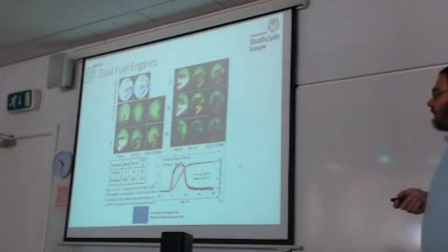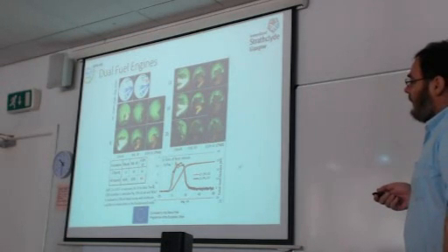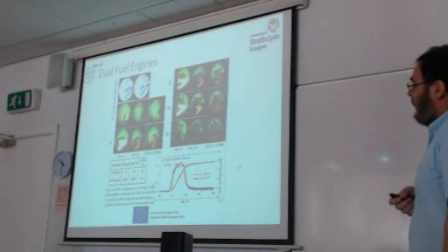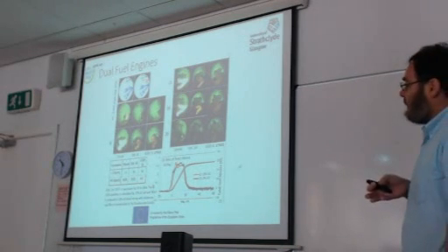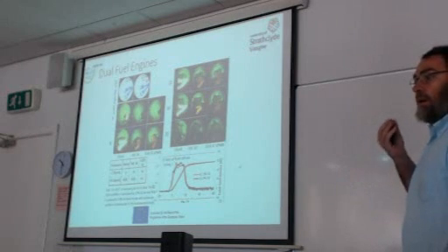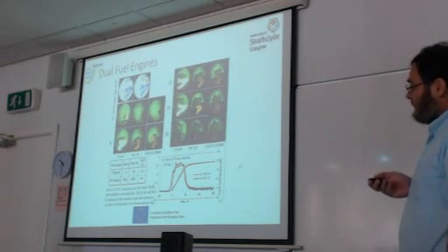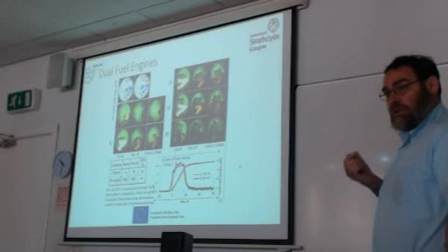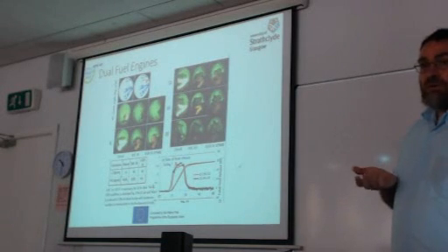If you consider that combustion of a liquid fuel is complex, then the combustion of a gaseous fuel and a liquid fuel is certainly more complex, but at the end of the combustion, the whole amount, or almost the whole amount, of both fuels, pilot and gas, is burnt. And of course, in this case, natural gas can replace the largest part of the diesel fuel. We need to know that for the pilot fuel, only 1 to 3% of the total amount of fuel is required. So this is the case.